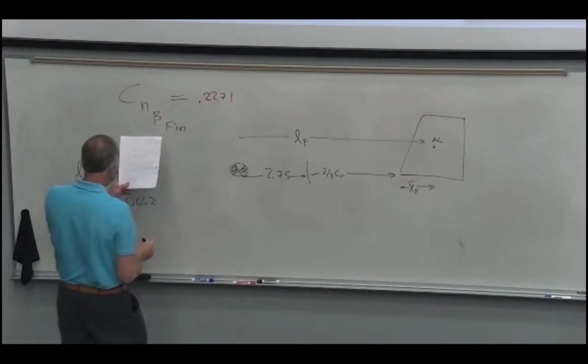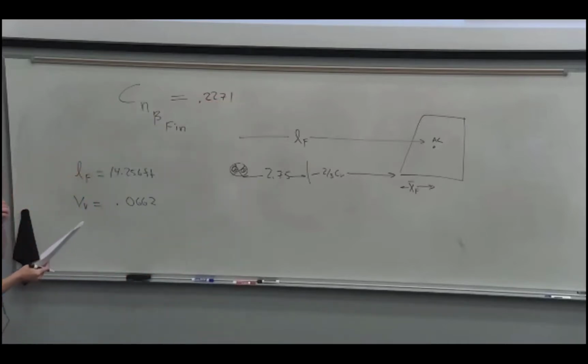You should get 0.2271. You need V sub V for that. You need the lift curve slope that you calculated in part one. You need the airspeed ratio, which we said just use 1, and d sigma by d beta was 1, right? That was 0.08. So that's just plug and crank.